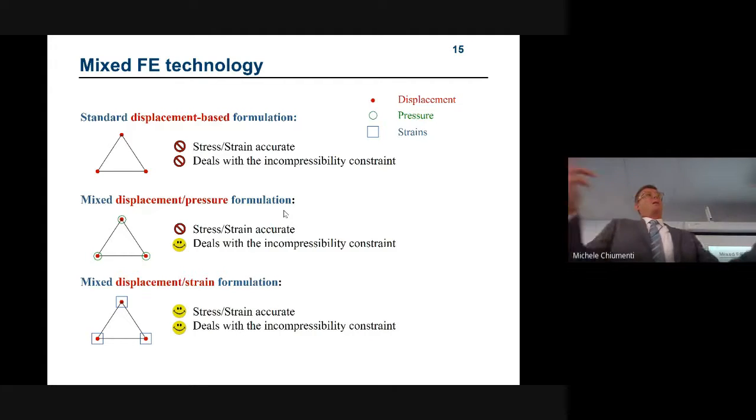You could say, okay, but if I have everything, so if I have isochoric problem, cracking, whatever, there exists another formulation that was just published in the last year, and one of the papers from this year is the three-field formulation, which includes displacement, pressure, and deviatoric stresses at the nodes. You can think this is very expensive and very complicated, but at the end, it's not like that. Okay?